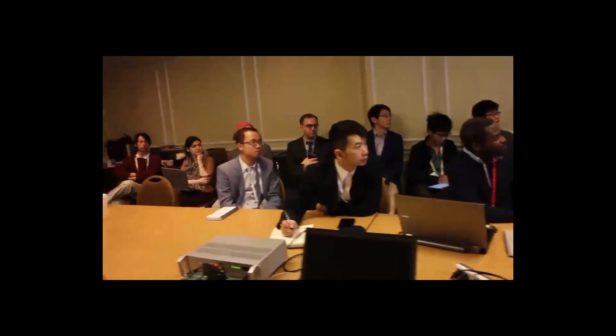Now you say, why are you doing such a crazy thing, Dr. Cuk? Well, because obviously I want to have two complementary switches on the input, which are rated at the input voltage. And then if I somehow can split this capacitance like in a Cuk converter into two capacitors, voila, here's my isolated Cuk Buck, right? It has a sound characteristic, D times something, and no input inductor, right? But this won't work because, why?